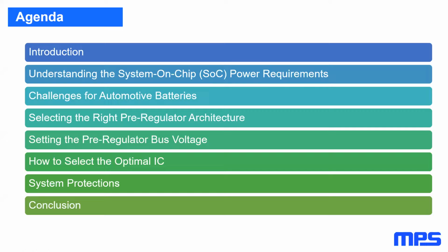So usually these kind of processors are traditionally found in computers, server racks, and they are powered from a clean or a relatively clean 12-volt bus or 48-volt bus. In the automotive environment, this is not the case. The car battery is nominal 12 volts, but it is very noisy. There are loads turning on and off, so it is more challenging.